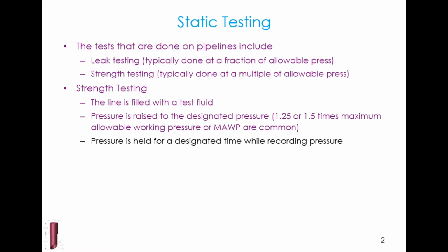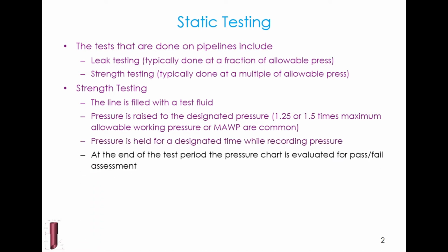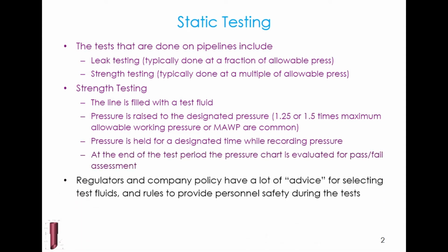Pressure is held for the designated time while recording pressure. At the end of the test period, the pressure chart is evaluated for a pass-fail assessment. Regulators and company policy have a lot of advice for selecting test fluids and rules to provide for personnel safety during the tests.